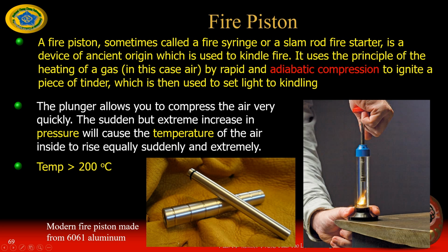Adiabatic, what does that mean? Adiabatic, 绝热. Okay, to ignite a piece of tinder, which is then used to set light to the kindling. So you can have a fire in this cylinder, or syringe. The plunger allows you to compress the air very quickly. The sudden but extreme increase in pressure will cause the temperature of the air inside to rise equally suddenly and extremely. So you push this piston into this cylinder,